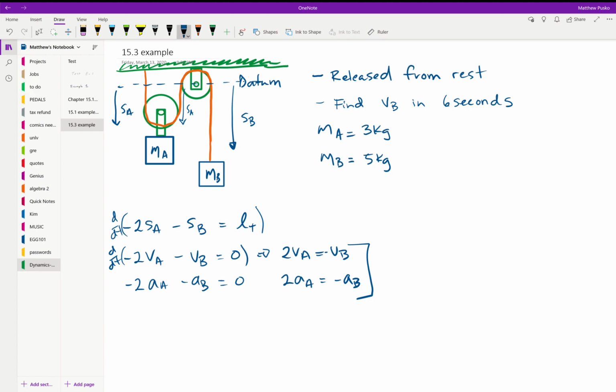We should now look at forces. So impulses involve the force integrated over time from T1 to T2. And you should start to notice after doing some of these problems that impulse momentum theory is very similar to what we were doing with work energy theory.